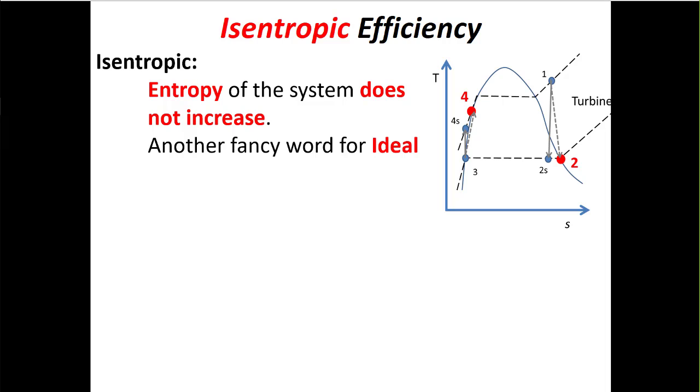So that's why we only talk about isentropic efficiencies for turbines, pumps, and compressors, right? So if it's isentropic, the process will be ideal if it is also at steady state, has one inlet and one outlet, and is adiabatic. Because then if I do my second law analysis, like we've seen, and delta S is equal to 0, then sigma dot must be 0, right?